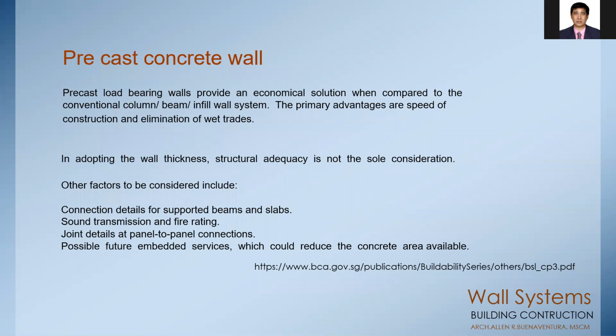In adapting the wall thickness, structural adequacy is not the sole consideration. Other factors to be considered include connection details for supported beams and slab, sound transmission and fire rating, joint details of panel-to-panel connection, and possible future embedded services, which could reduce the concrete area available.